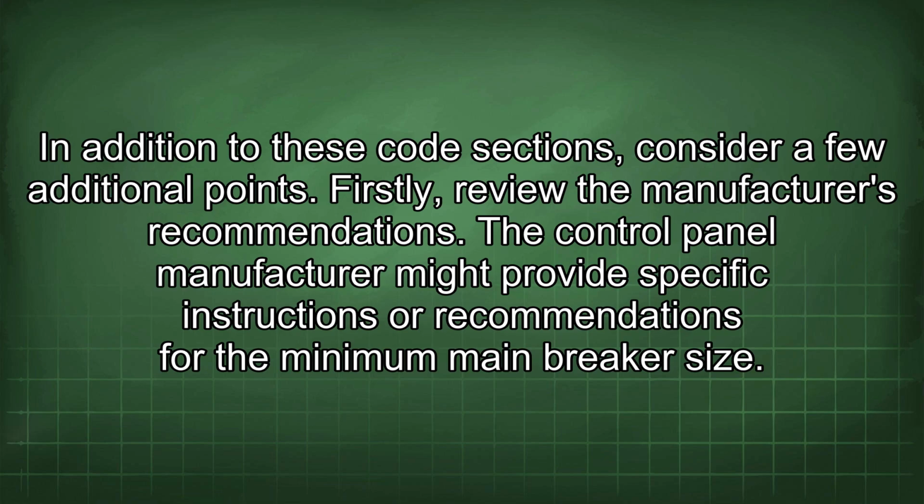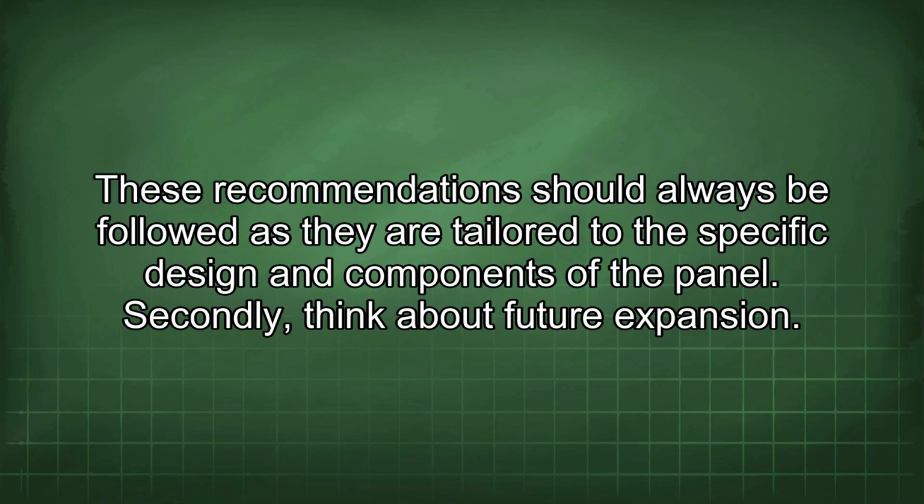In addition to these code sections, consider a few additional points. Firstly, review the manufacturer's recommendations. The control panel manufacturer might provide specific instructions or recommendations for the minimum main breaker size. These recommendations should always be followed as they are tailored to the specific design and components of the panel.